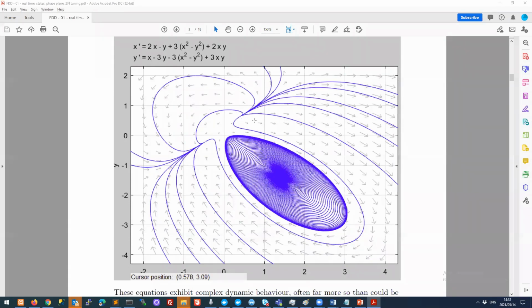So this is, in a sense, the opposite of what might be your current understanding of steady state. You think of steady state as a stable thing where you get to steady state and everything lives happily. Well, this is also a steady state, but this is what we call an unstable steady state. If you sit exactly on the steady state, you will stay on that steady state. But the moment there's a slight movement away from that, the moment your system is disturbed slightly, the system will quickly push you away from that steady state. So that's what we call unstable steady state.